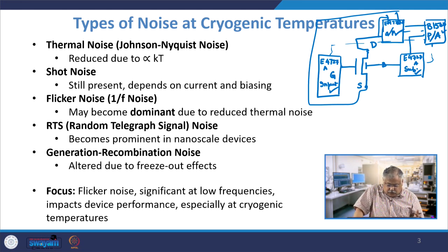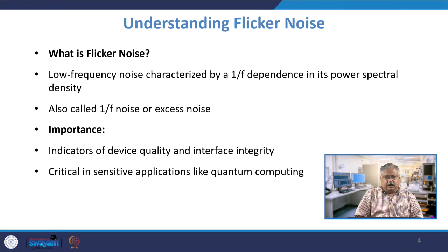So this was basically done by the authors on a Lakeshore cryogenic system probe station, and they were able to finalize the values of 1/f noise at 8 Kelvin. So this temperature can go up to approximately 8 Kelvin to 10 Kelvin range, measurement can be done in this case. Okay. Now, as I discussed with you, coming back to the original discussion, if you have generation recombination, noise is not there. So that is the reason we are concentrating more on the 1/f noise in this sense.